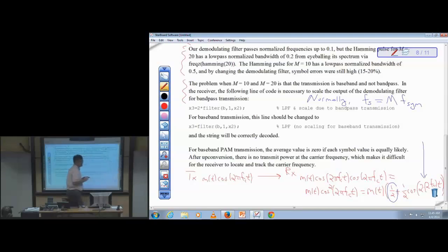So they are related. But in this case, we forced the sampling rate to be M, which did throw some things off. In other words, you could argue our symbol rate was 1. There are lots of ways you can argue this. So they can't be completely decoupled, because there is this relationship between the symbol rate and the sampling rate.